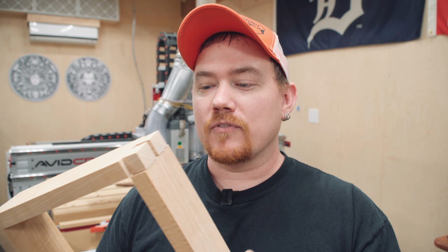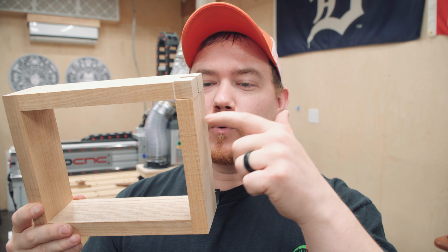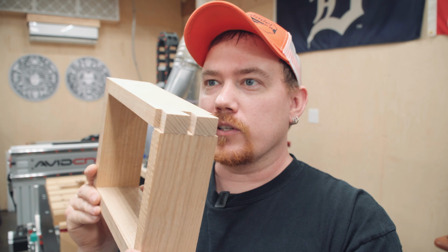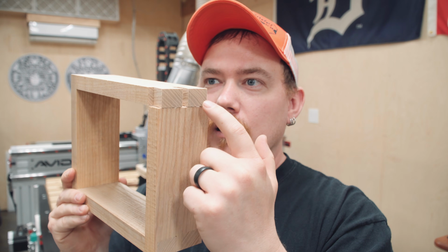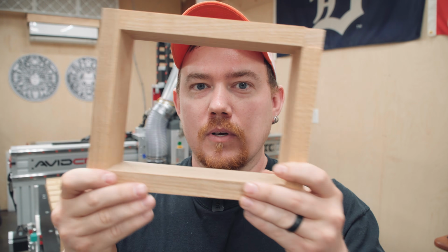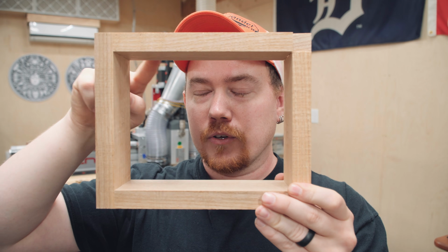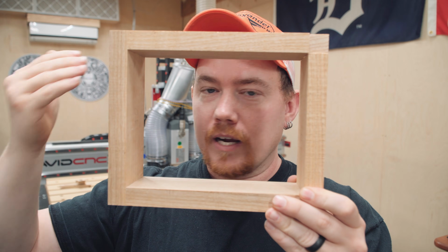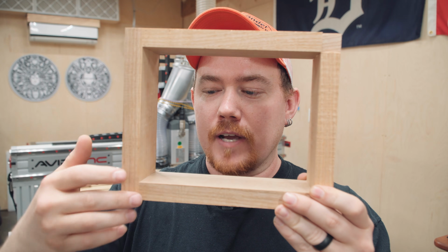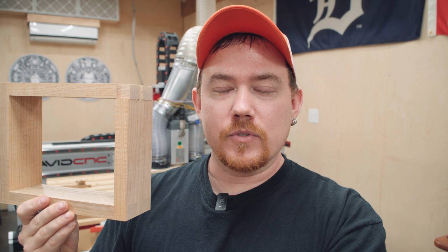Now to take that a step further, I did a little box here, but I cut one board short, so there's no pins on this board, as you can see. And that means after 1, 2, 3 joints cut and fit on this machine, your level of error is magnified every single time, or it's an additive error all the way across, kind of similar to the 5-cut method when you're trying to set up a table saw sled.